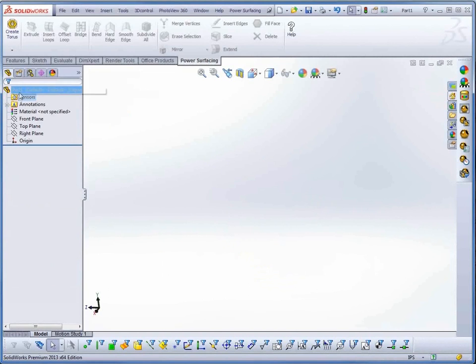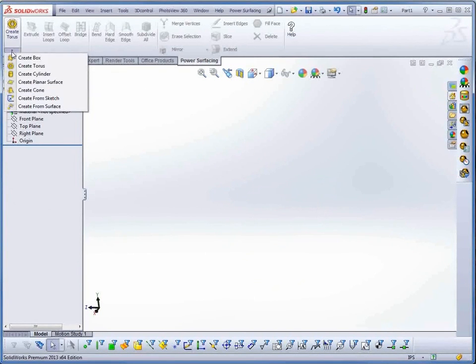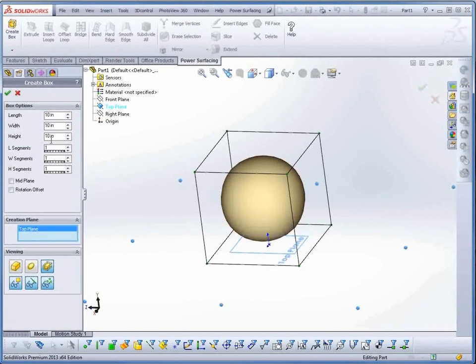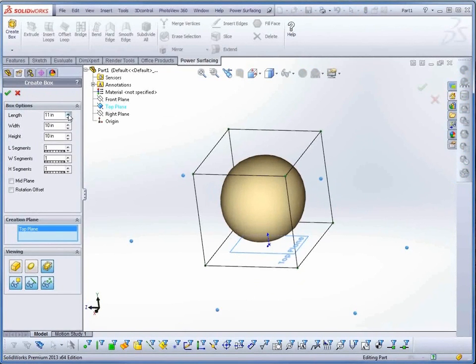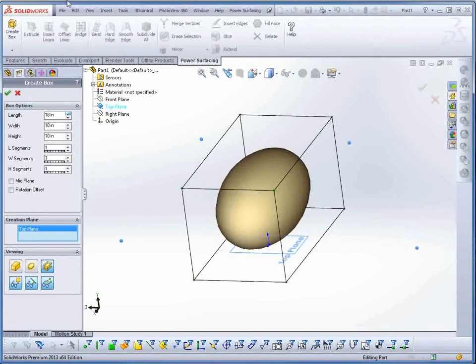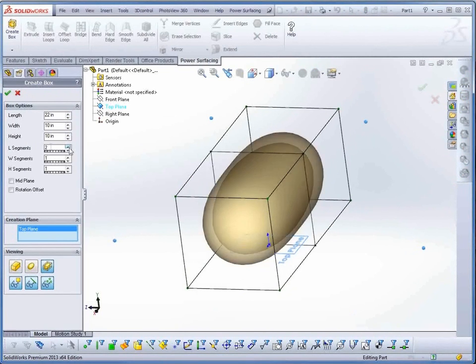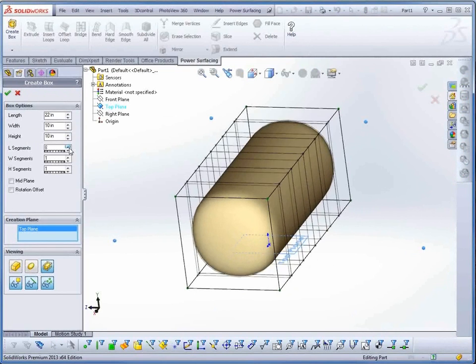You can also set the base dimensions and topology during setup. The secret to efficient Sub D modeling is to work with a minimal amount of geometry as long as possible. Best practice is to avoid adding segments until you actually need them.